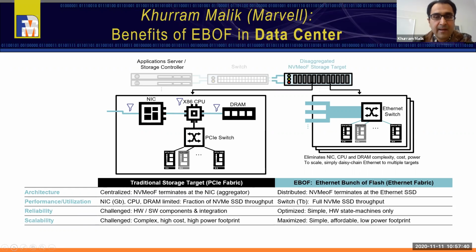As you can see, this architecture replaces all the bottlenecks we can encounter on the very left side with the Ethernet switch. The PCIe, the CPUs, the DDR, the NICs are replaced with a simple L2 Ethernet switch, and on the front end, customers can use the standard Ethernet SSDs.